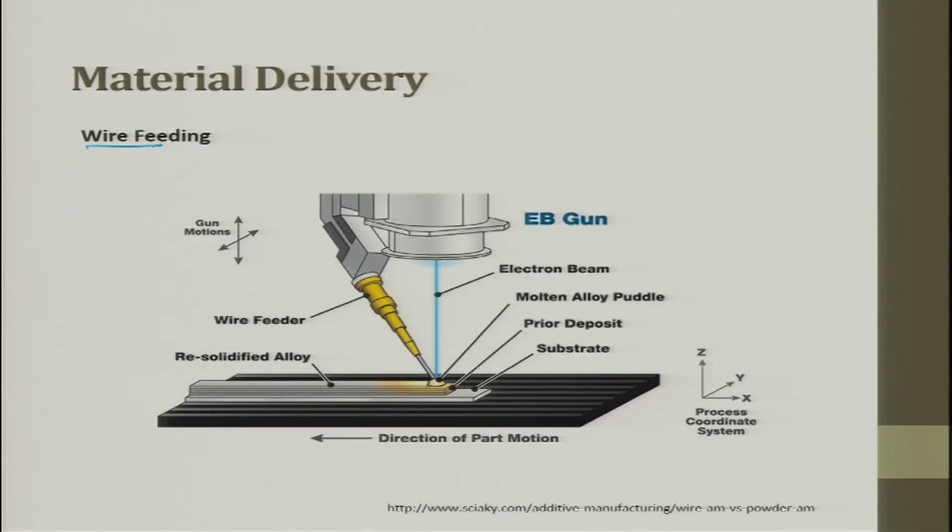So, wire feed. So, this is the wire which is getting fed. It looks like your MIG system and TIG system. So, this is a wire feeding coming up. Here is a laser. So, this laser or the electron beam comes and hits at the pool, and here it melts. Here is a melt pool we talk about. So, this is the molten, they call it puddle, we will call it melt pool. So, this is the wire coming here, electron beam can be replaced by laser.